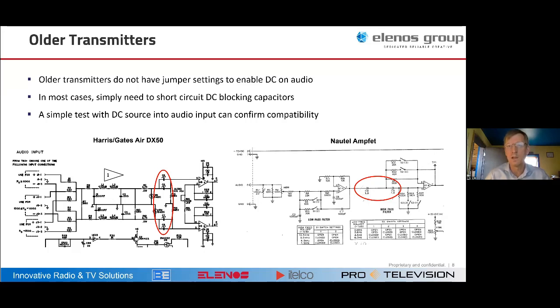Most transmitters, with the exception of Nautel's NX, require external mag and phase inputs, which are essentially analog signals to drive them. So if you can find an exciter that will give you those mag and phase signals, any modern AM transmitter will run MA3.